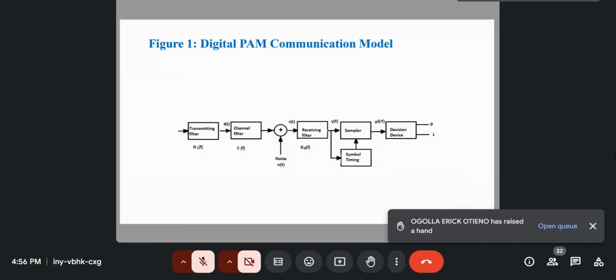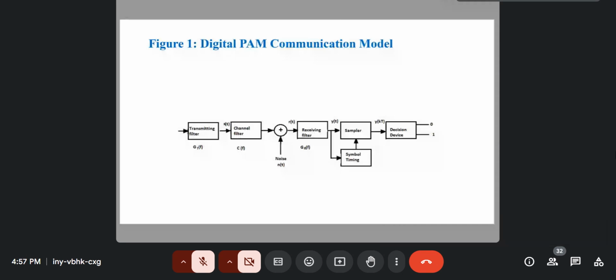So even probably the spacing of your antennas, I mean how close the antennas are to each other, because we are talking about wireless communication. So you have to consider that, and you have to mitigate against that. Maybe even the type of error control, because once you have interference, you get errors. So you have to have very robust error correction and detection methods.